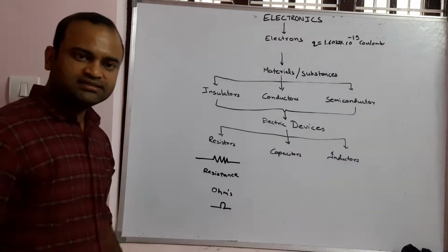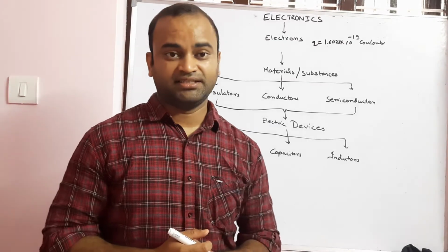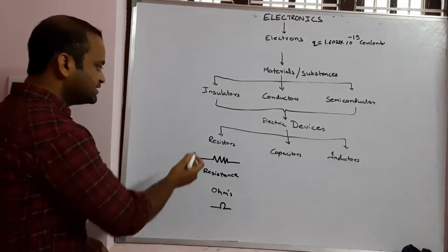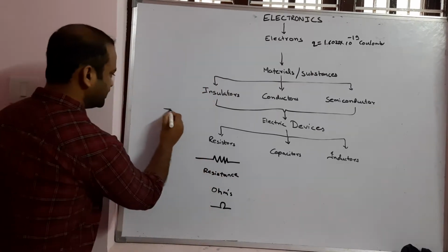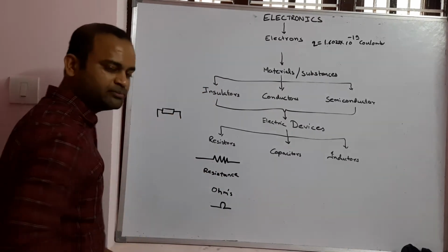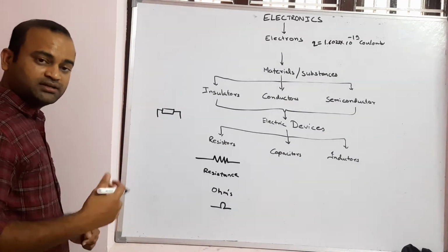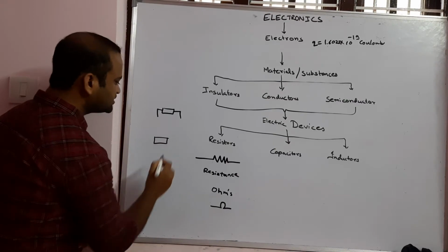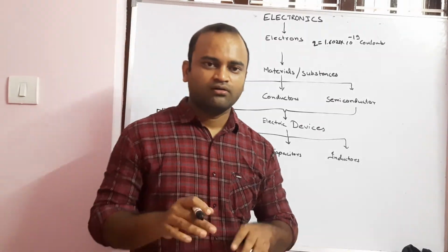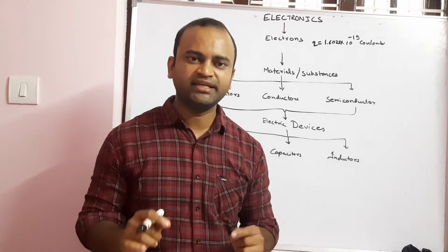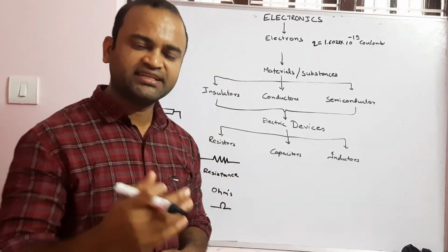Now resistors in electronics, when you do a design, come in various packages. Package is the construction. For example, these resistors can be obtained in leaded format. That means the resistor can have two leads and is known as a through-hole or leaded component, or an SMD. SMD means surface mounted device. That resistor can be mounted on a PCB and soldered without going through holes of the PCB. So you don't need holes made on the printed circuit board to mount the resistor if it is an SMD package.